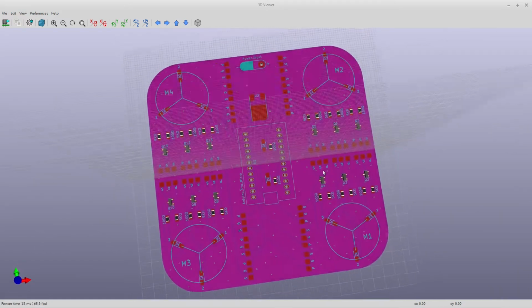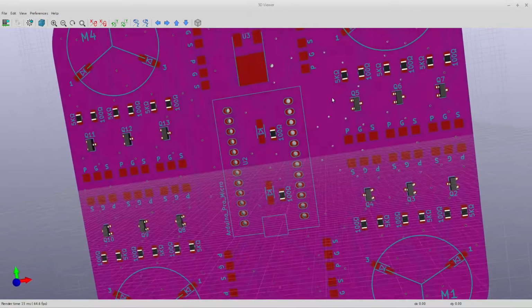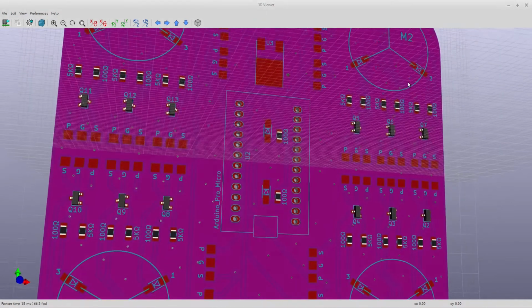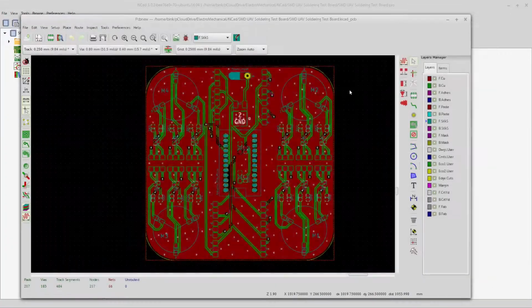So this is nice. This is a section where you actually define, like in the last video, our 100 ohm resistor that we soldered on. I made this pad right here, the footprint they call it, that this is going to span based upon what the data sheet of this resistor said that its length and width was. And then you give yourself a little extra, this little extra right here, so that we can solder. Again, from the last video, that gives us a little bit of extra pad there to create a nice little fillet. So I'll close that, come back to this.